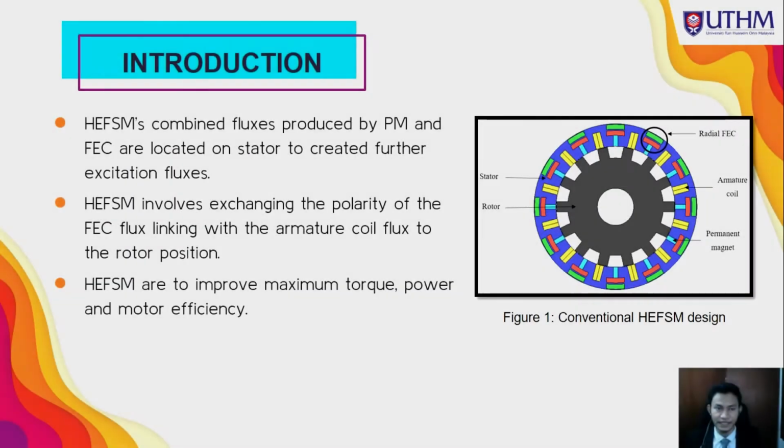For the introduction, the HFSM is an upgrade from the PMFSM, the Permanent Magnet Flux Switching Motor, and also from the FEFSM, the Field Excitation Flux Switching Motor. The HFSM, the Hybrid Excitation Flux Switching Motor, combines flux produced by the permanent magnet and the FEC located on the stator to create further excitation flux.